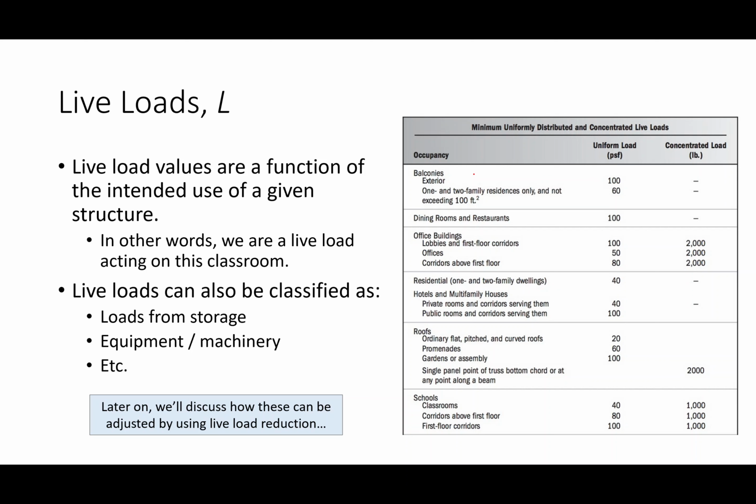And specifically, corridors on the first floor are probably going to have a little bit more traffic. But what's another reason? Why would we want the load to be a little higher in the hallways? Fires. There you go. When there's an emergency, there's going to be a lot of people in the hallways, so we need to make sure the building can account for that. Good answer.